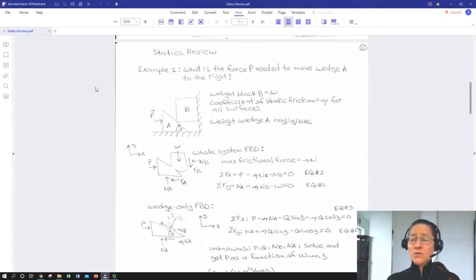Because in all cases, we will need to know what forces and moments we are actually applying to a body before we start looking at how those forces and moments will work with the geometry of the body to translate into an applied stress, and then how the material properties of that body are going to react to that stress and result in a measurable strain. So it all starts with the applied forces, which will result in applied stresses, and that all flows out of our conditions of equilibrium.